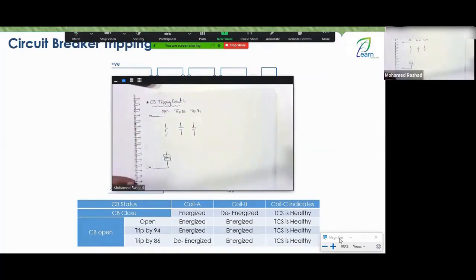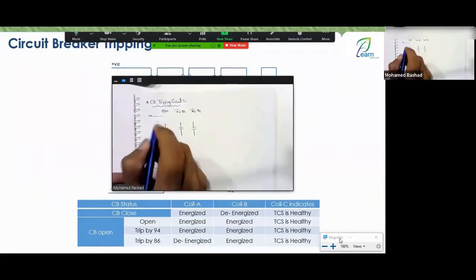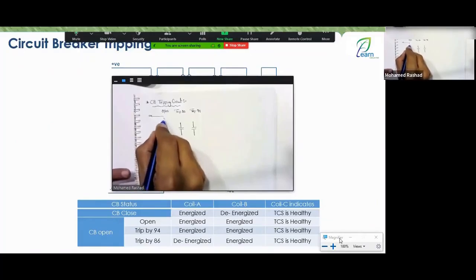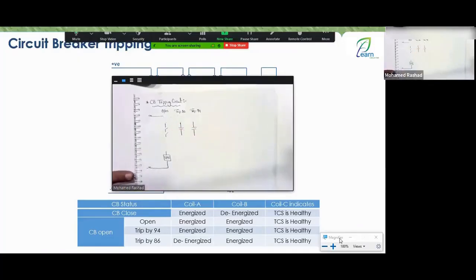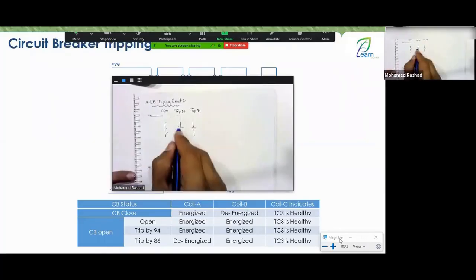Okay. So what's happening? What's happening now is that he's afraid, now that I've connected all these things, for example, like this, in parallel in this way. Okay. Very good. He's afraid now that if the supply cuts off, I don't see that there's a problem for me. Okay, if I put this supervision at the end of the circuit, this supervision monitors the positive from above and the negative from below. So if there's a problem with the trip coil, if there's a problem with this contact, will I know? No. Okay, if there's a fault, will the breaker open? Also no. So what's the solution?